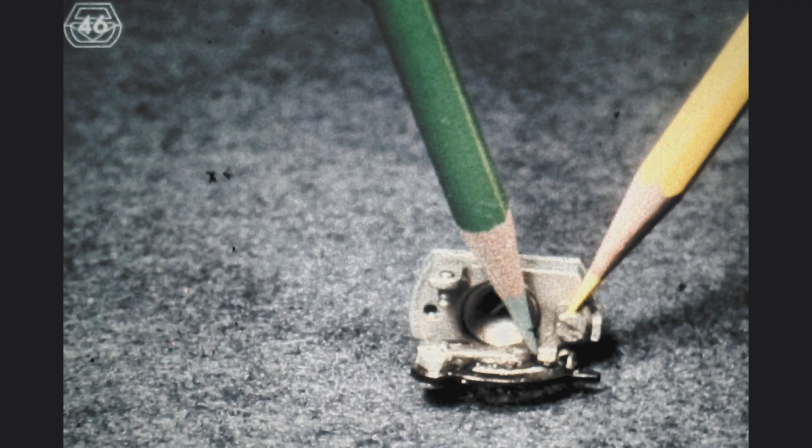To adjust the position of the rotate shoe, we loosen the screw indicated by the yellow pencil. This, however, is not always easy, because when the tilt ring is installed in the machine, this screw is not easy to reach. With an offset screwdriver, or a very small screwdriver that fits into the slot sideways rather than from below, it is possible to loosen the screw. Moving the shoe by only a small amount and tightening the lock nut enables us to eliminate the side play of the rotate detent. Be sure not to create any bind for the rotate detent.